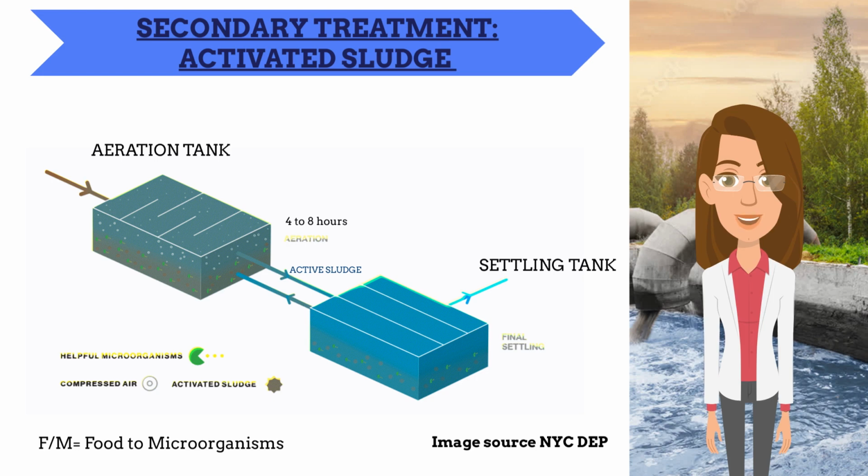This process must be meticulously monitored and controlled to maintain the proper ratio of substrate, organic load, to microorganisms, the food to microorganism ratio. The waste rate or wasting rate determines the F/M ratio. The higher the wasting rate, the higher the F/M ratio. Hence, a lower F to M ratio means the microorganisms in the tank are starving, which results in more efficient wastewater treatment. Important parameters are as follows: organic loading rates, oxygen supply, and control and operation of the final settling tank.